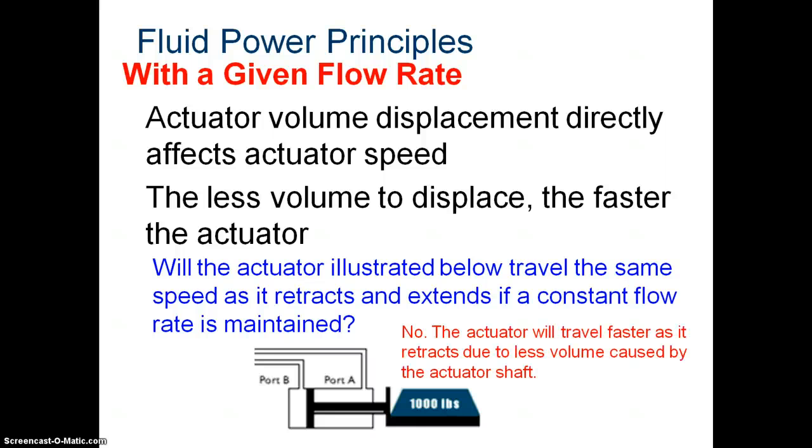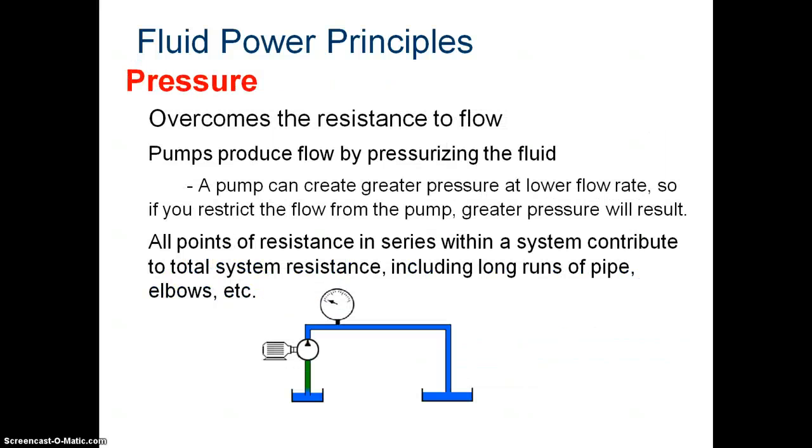No. The actuator will travel faster as it retracts because there's less volume caused by the shaft. Pressure overcomes the resistance to flow.